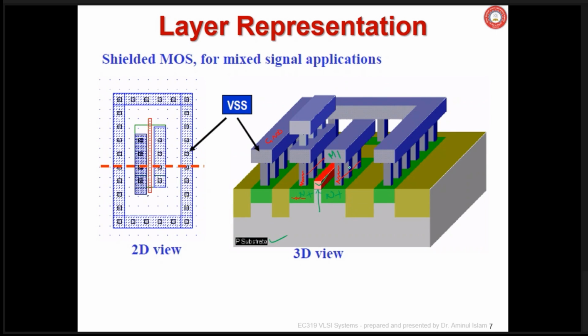If you have made only one contact and it is failing, it means that while filling the hole, the complete connection is not made. You know how this metallization or filling is done? By CVD, chemical vapor deposition. The metal will be in the evaporated form and it will be deposited gradually in the hole. So while filling the hole, it may not be perfectly made. To avoid that, multiple vias are made, and hence the chance of that kind of failure will be avoided.